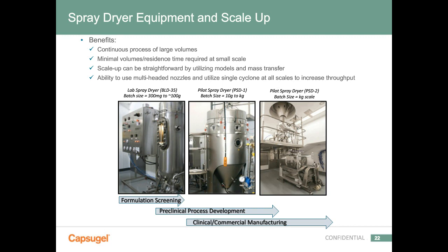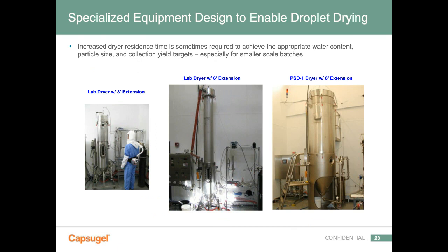We've also identified a couple different specialized equipment designs to help enable droplet drying. Because you're using water as a matrix, sometimes these materials slowly diffuse, and if you do not have the necessary drying time within the dryer, you'll get impaction on the side walls of the spray dryer or even the pipework prior to the collection vessels themselves.